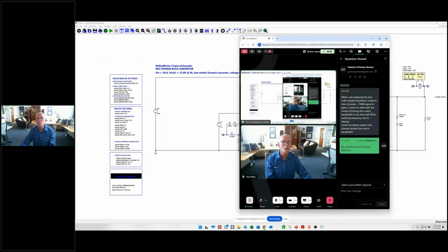Well, we have something on our website that shows why you can't go above half the switching frequency. I was thinking of including that in this webinar, but it was too much. You cannot go above half the switching frequency because the phase margin will always go to zero at half the switching frequency.